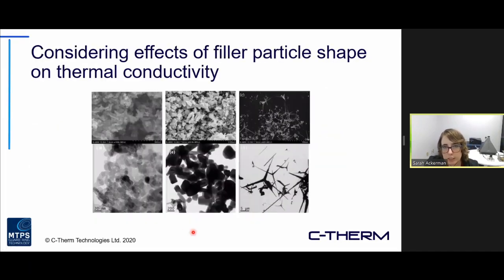The particles that they included were a nanoplatelet, a spherical particle, and then this kind of sharp and pointy shaped particle that they call a T-shaped particle, which is intended to improve the heat transfer efficiency and have a high aspect ratio, to improve basically thermal communication between the filler particles.